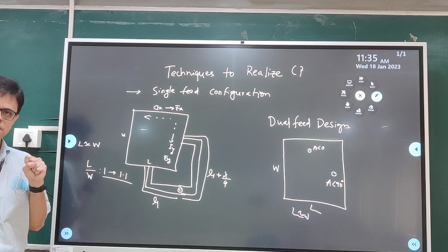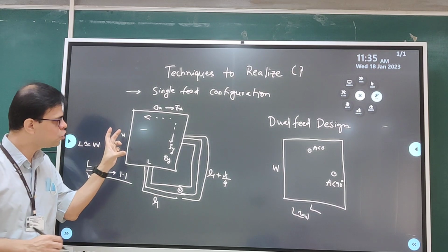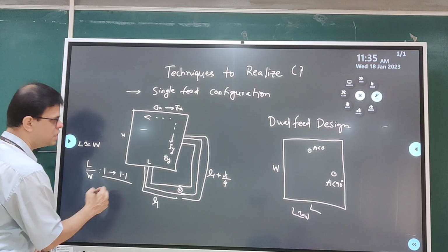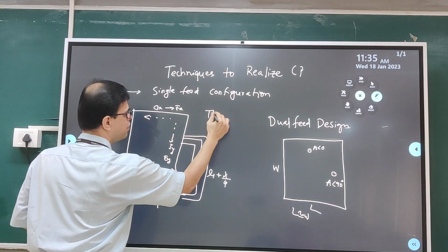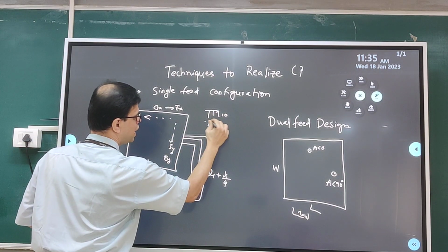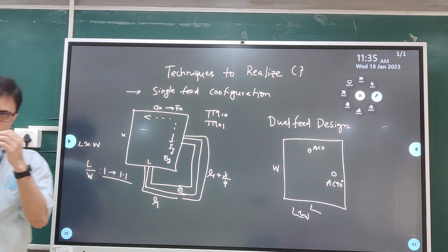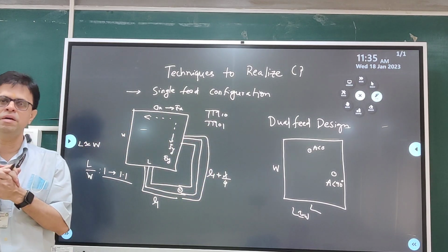Now to achieve this, I need to excite orthogonal modes in the patch. The orthogonal modes in the patch are TM10 and TM01.